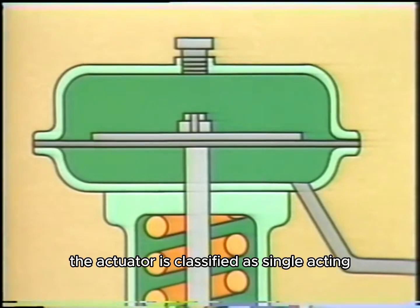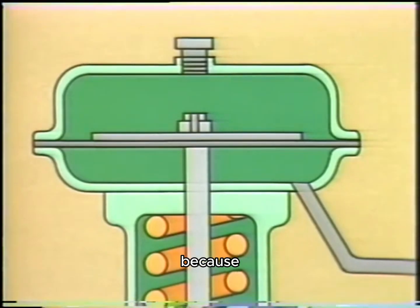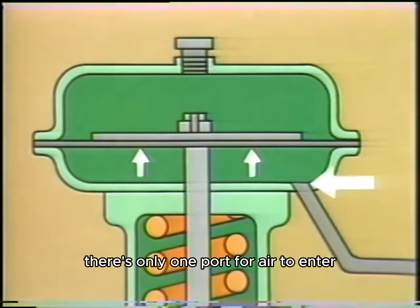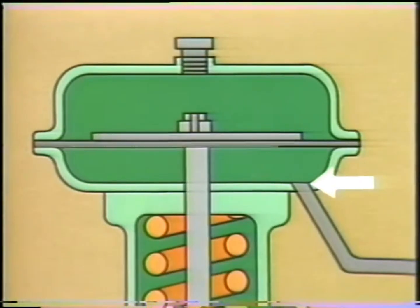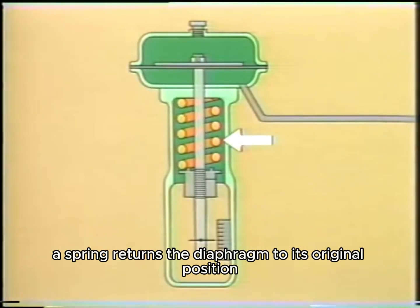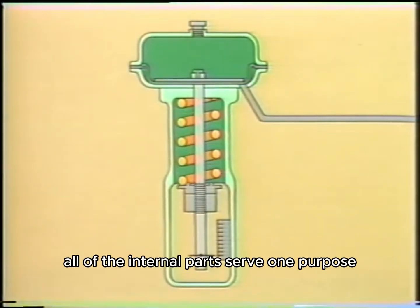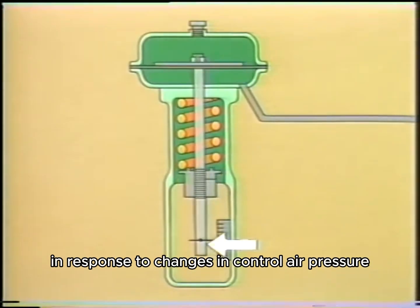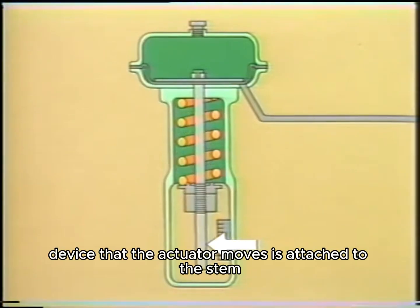The actuator is classified as single-acting because air pressure acts on only one side of the diaphragm. There's only one port for air to enter. When air pressure is removed, a spring returns the diaphragm to its original position. All of the internal parts serve one purpose: to move the stem of the actuator up and down in response to changes in control air pressure. The device that the actuator moves is attached to the stem.